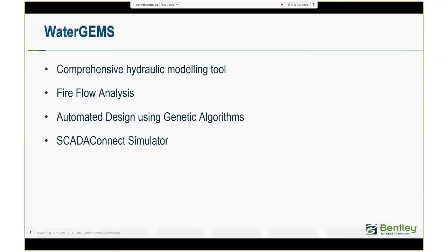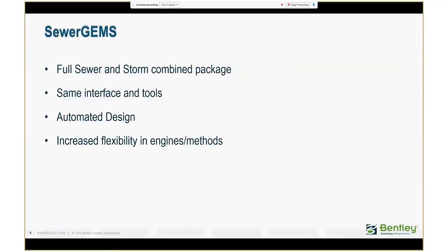And then the simulator, as I said, SewerGEMS. It's named SewerGEMS, which is slightly misleading. SewerGEMS, in fact, has all sewer and storm functionality within one product. It's just that it was originally named SewerGEMS, and the name hasn't been changed to reflect the storm part of it. So it's got the same interface and tools as WaterGEMS.